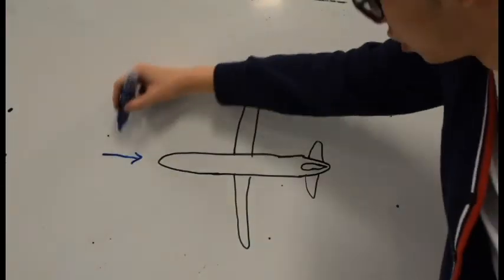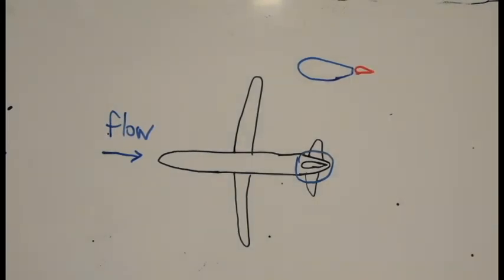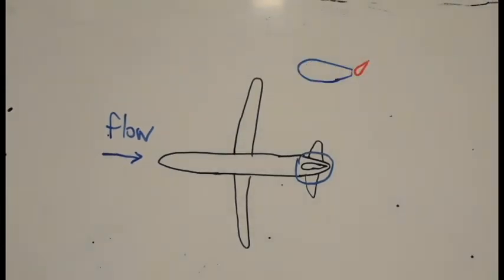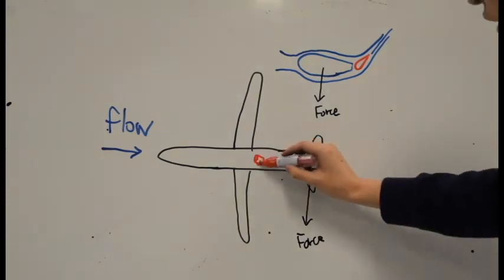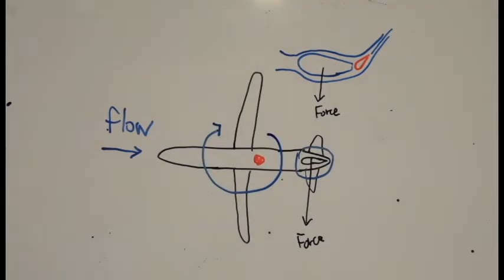By a similar manner, the yawing motion could be adjusted through the adjustment of rudder angle. To get a positive yaw, which means yawing the aircraft to right, it could be done by applying a right rudder. But actually, yawing is not frequently used in air, and in fact, the use of rudder is mostly on ground, like during taxiing, and when there is some slight slip of wind.